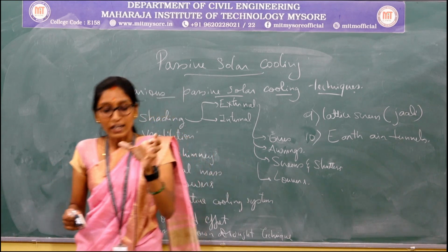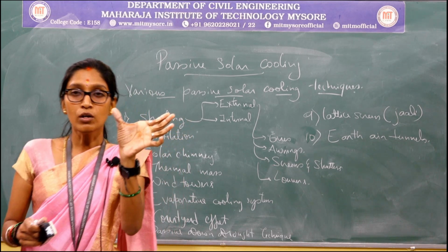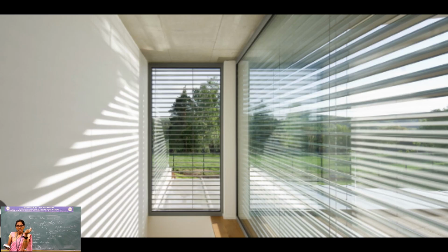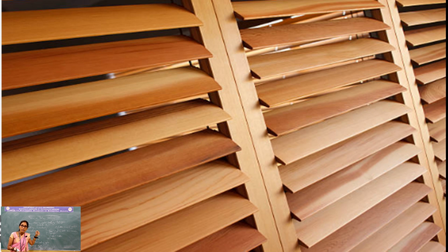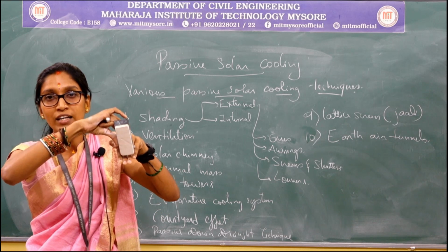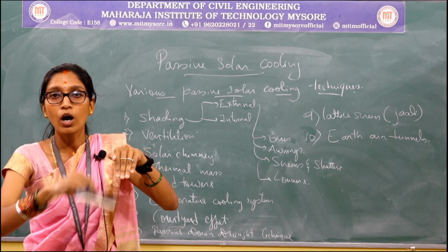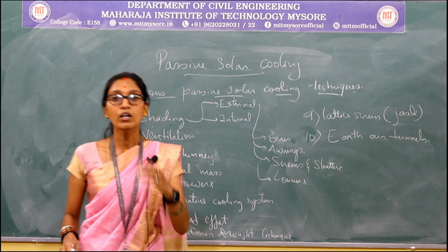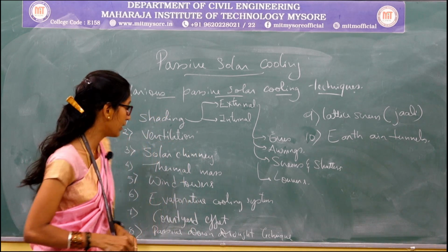How do they look? They are nothing but the planks or the slats of wood or a particular material, in a rectangular form, and slightly bent, which provide privacy to the interiors as well as free circulation of air through these louvers. At the same time, the entry of sunlight is also trapped or rejected. So these louvers can also be utilized to have a good shading effect in a building.